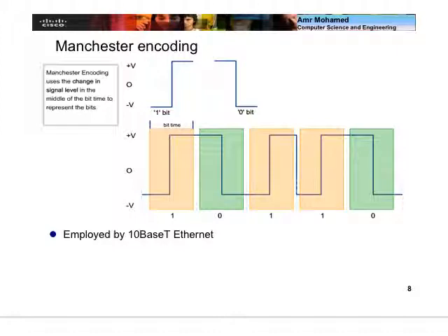Basically it represents the 1 using a change of amplitude like this, and the 0 the same signal but with 180 degrees phase shift. It's like it's reversed. So the 1 is like this, and the 0 is the mirror of it. So this tends to fix most of the problems of the non-return to 0 encoding scheme.